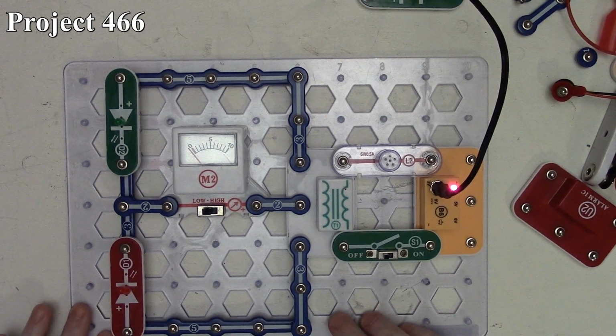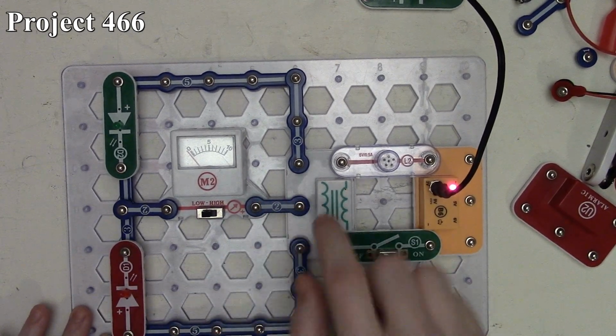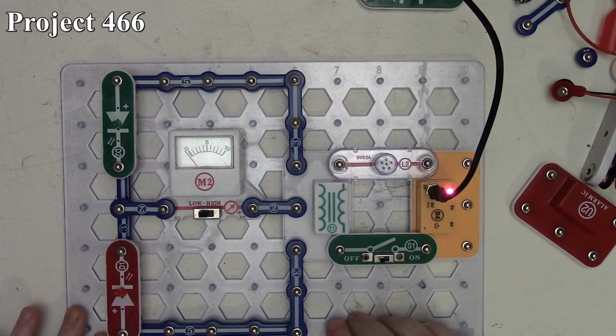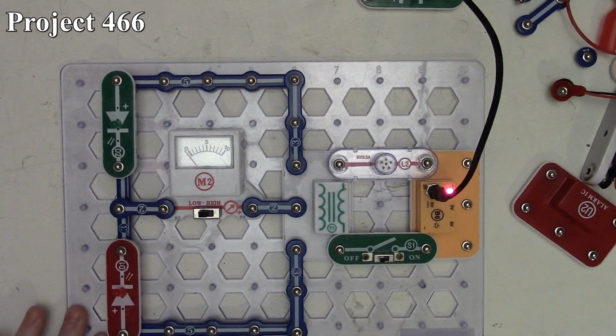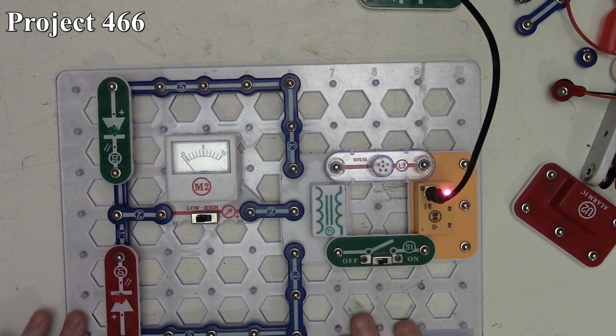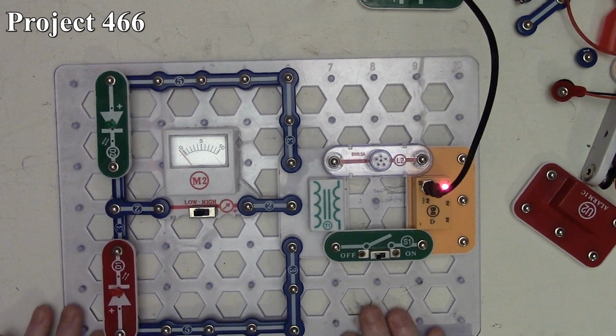And in Project 358, the green LED lit first, and then the red when we turn the circuit off, because again, we're creating an alternating current with our transformer here. Of course, the opposite is going to happen here, where our red LED lights first, and then our green LED when we turn the circuit off by turning it on and off. So we'll see that. And of course, our 6-volt lamp here is just to both limit the current, but also illuminate when the transformer is energized.